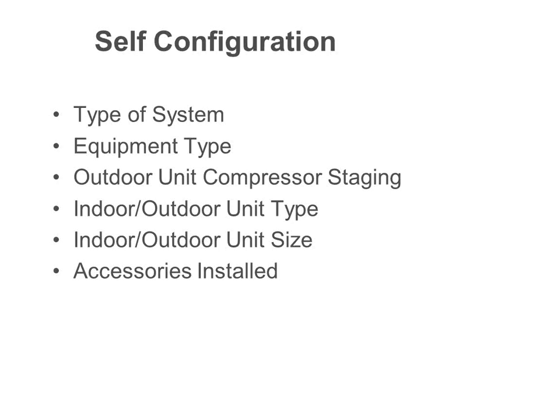Based on that information, it can do some of the configuration stuff on its own. For example, if it sees it has a 3-ton outdoor condensing unit, it'll tell the furnace which fan speeds to use for that 3-ton condensing unit. So it'll say, okay, based on whatever, 350 CFM per ton, for a 3-ton condensing unit, I need 1,050 CFM at full cooling. I need whatever, 700 CFM at single stage cooling. So it'll do all that for you without you having to think about it or configure it or anything like that.